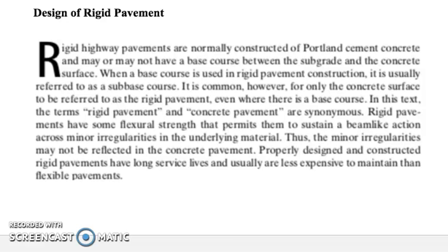So of course, rigid pavement, as mentioned, is constructed with a Portland cement concrete slab resting on a prepared subbase or granular material, or directly on a granular subgrade. So the load is transmitted through the slab to the underlying subgrade by flexure of the slab. The flexible pavements are constructed of several thicknesses.